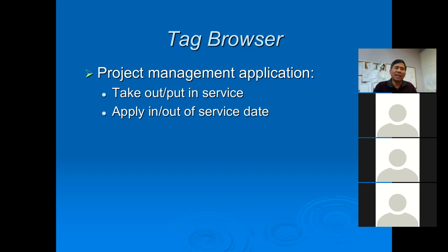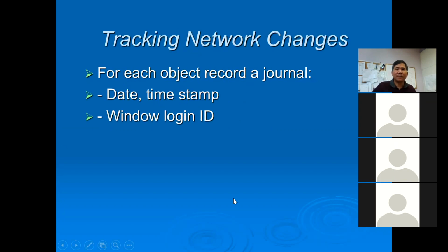You can also use the tag browser if you specify the in-service date and out-of-service date. That way you can link the project in-service and out-of-service dates to the tag and take them in and out of service. Okay. Now, the program also now records a journal entry every time you edit something.